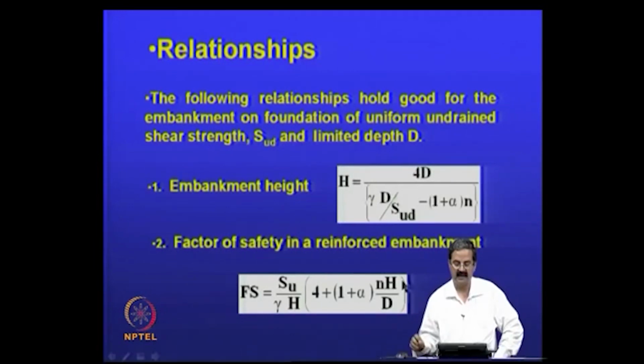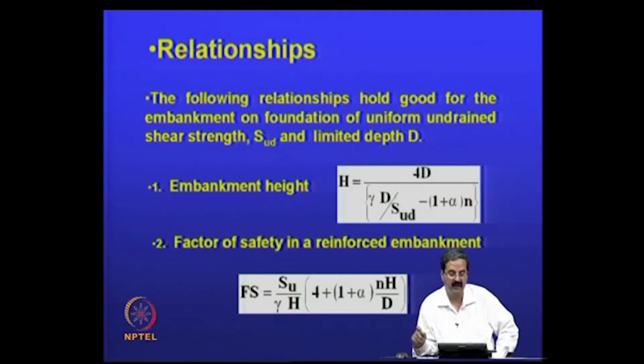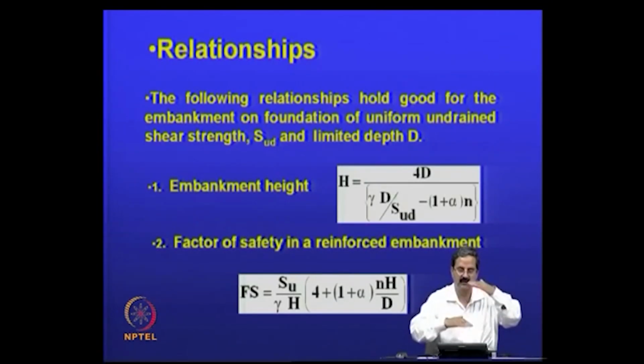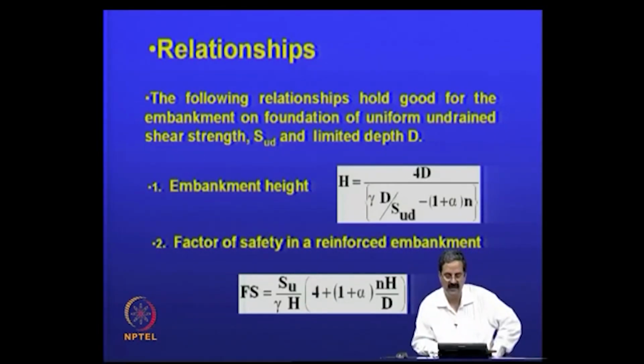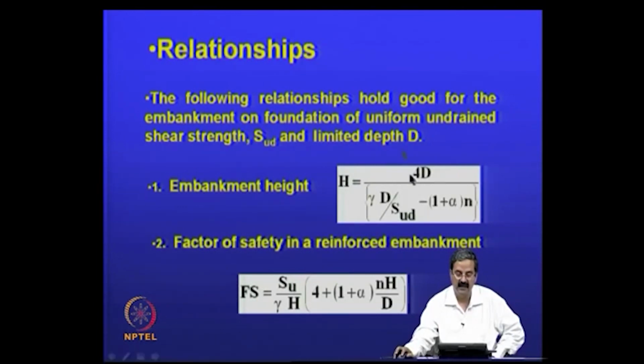Based on that, we are using that factor called alpha here. When inward and outward shear stresses are equal, you calculate the block equilibrium and equate it to the n required, that is what we have seen. On the same logic, you can even calculate the height of the embankment. So if alpha is 0, the inward shear stresses are equal to outward shear stresses, but if alpha is quite substantial, then it comes into the picture.